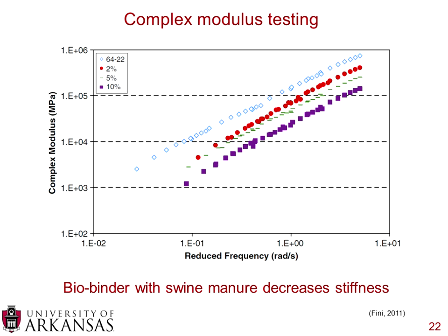Decreasing viscosity means that your material flows easier, and you would expect to see a decrease in stiffness, and that's what you saw here. So these are the master curves. You have the complex modulus versus your frequency. As these curves shift downward, the material is becoming less stiff.